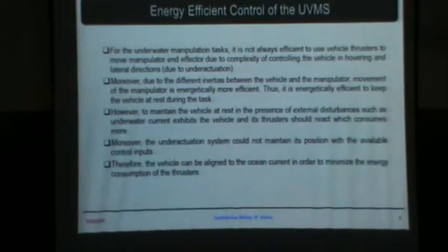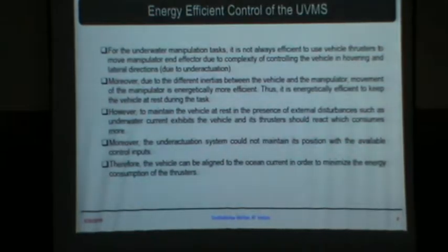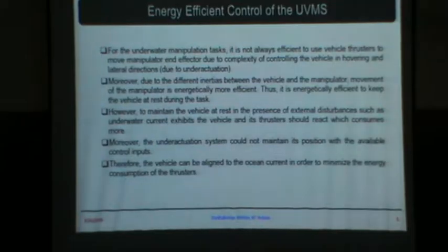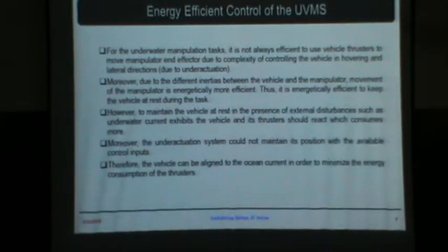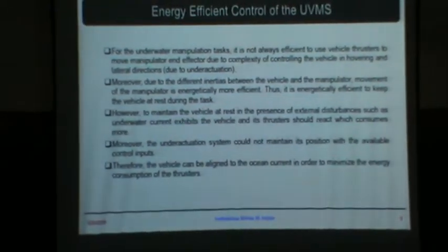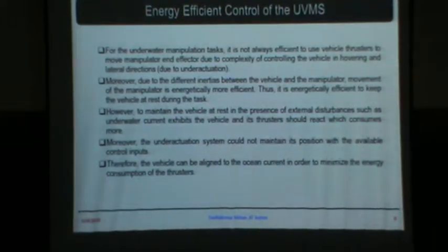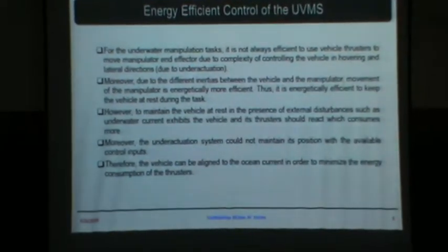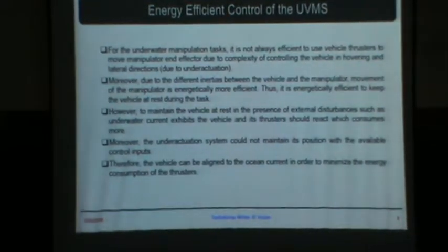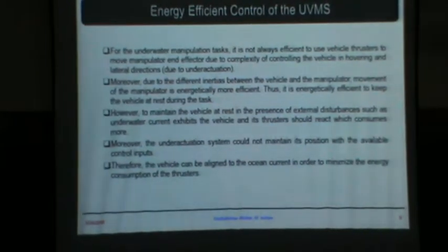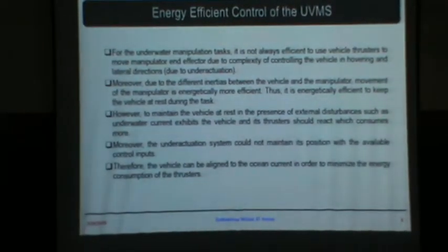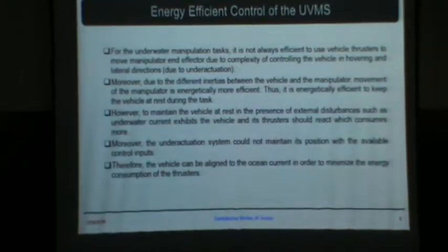If you put a drum in moving water, automatically the drum will move and align like this. Did you notice that? How is it happening? Nobody told it to change direction and go. This is what we call self motion. For example, take an underwater vehicle, inside water, with an underwater current passing over it. If you have a larger frontal area with the current hitting the lateral side, it is a large frontal area, so more drag force.